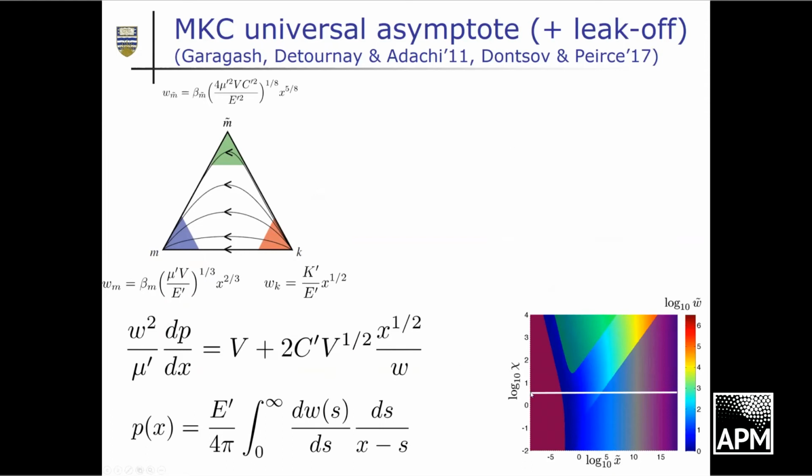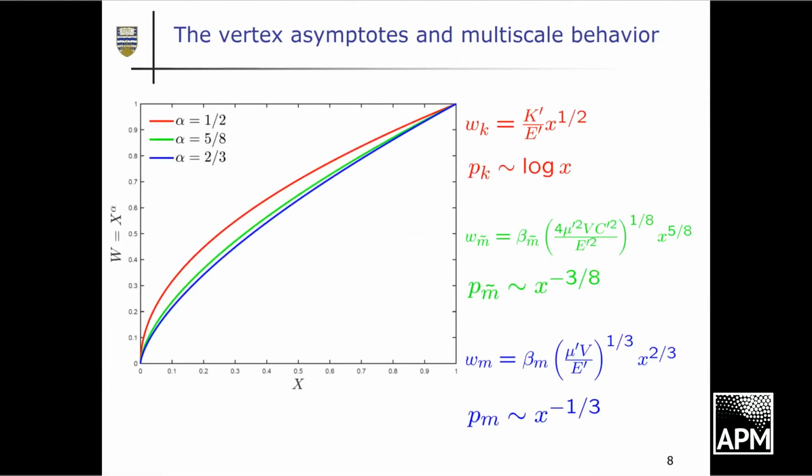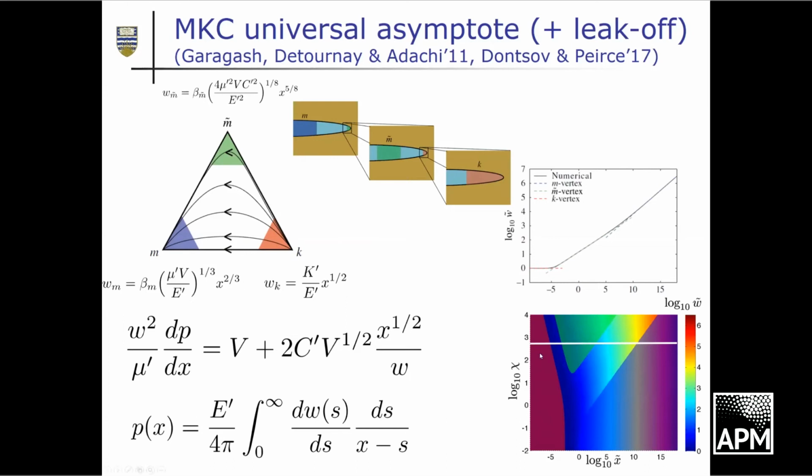But basically, if you do a cross-section over here, you'll see that if you're close to the tip, you'll go from the toughness regime, which is in red, to the viscosity regime. So this is a section here, which is this white line. If you go a bit higher up in this diagram, later in the process, or for a different set of parameters, if leak-off is present, for example, or becomes more dominant, then you can go from toughness to leak-off to viscosity.